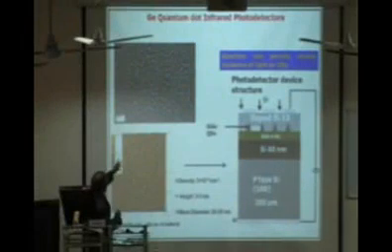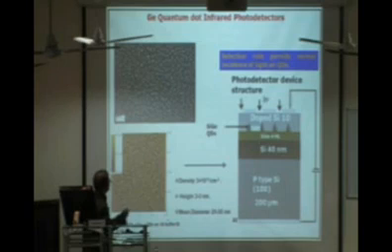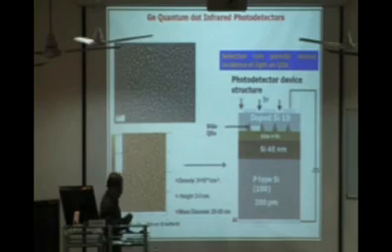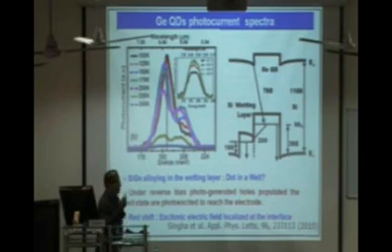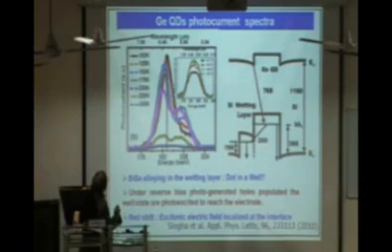So what about the quantum dots that we grow in our MBE? Actually, they are very large area quantum dots. In the structure, we put a silicon substrate, and then we put some kind of dopants into it. And finally, we made the response in the so-called mid-infrared range. We are trying to make a mid-infrared detector; the typical good wavelength is between 8 to 12 microns. But with our quantum dots, we got good photo response only at about 6 to 7 micron wavelength.